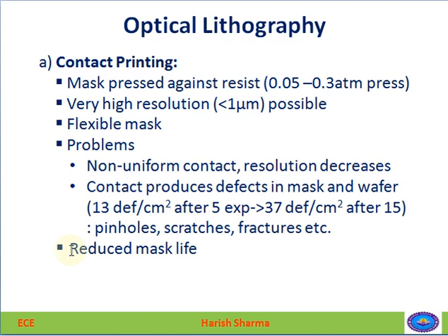So there will be a decrease in the resolution, and because of the contact between the resin of the resist and that mask, the mask is just damaged. There may be pinholes, scratches, fractures in the mask or in the pattern on the resist. So it will reduce the life of the mask also.